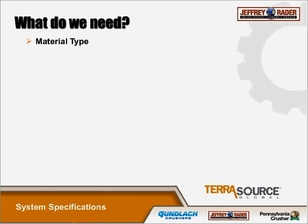So what do we need to be able to give you a pneumatic system? We need to know the material type. This determines several design factors, including initial velocity, which we'll go over in a minute. All these specifications are critical because they define a unique system. If anything's changed, the system will not work properly. We would need to know about it so we can make necessary upgrades or changes to the system.